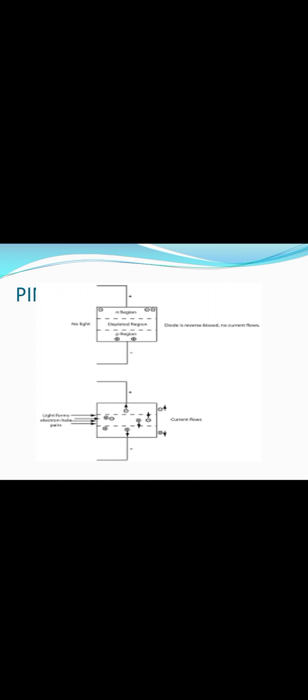In these circuits, the rise time or transit time, which is large in the wide regions, limits the speed of response of the fast PIN diodes. Rise time is limited by the transit time. It ranges from about 0.5 to 10 nanoseconds. The lowest rise time, less than 100 picoseconds, has been attained for PIN diodes. These are the characteristics of PIN diodes and avalanche photodiodes.